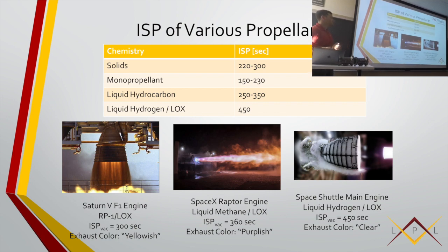So, which is good, and that's why you'll see hydrazine used where things need to work. But the downside is your chamber erodes over time, and you need to take that into consideration. But as you can see here, for monopropellant, you don't get as much energy generated from it. So you're around 150 to 230.